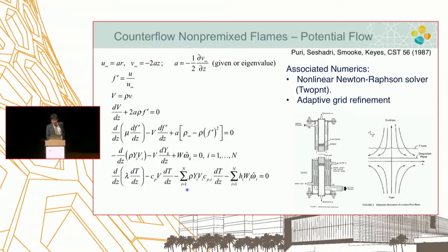And finally, the counterflow. This is, again, the most commonly used. Not too many people in today's combustion world know about it, because everybody's using OPPDIF. But before that, Mitch Smooke designed this more like a theoretical formulation about doubly infinite counterflow, which is consistent with Liñán's mathematical model. So here, fuel and oxidizer come from infinitely far away, and that way you can construct a nice theoretical Hiemenz flow field,